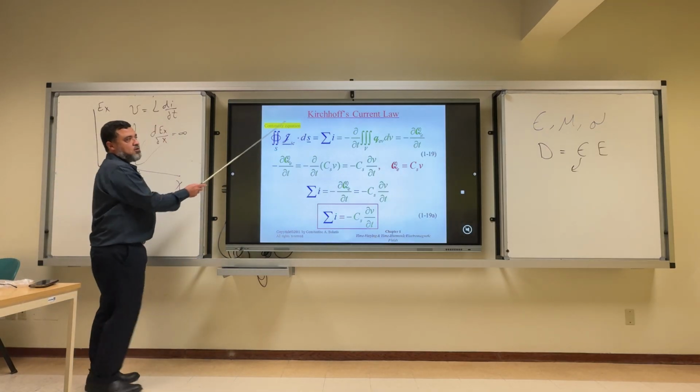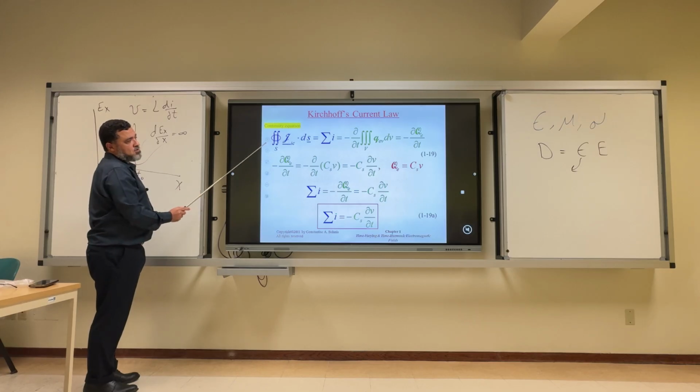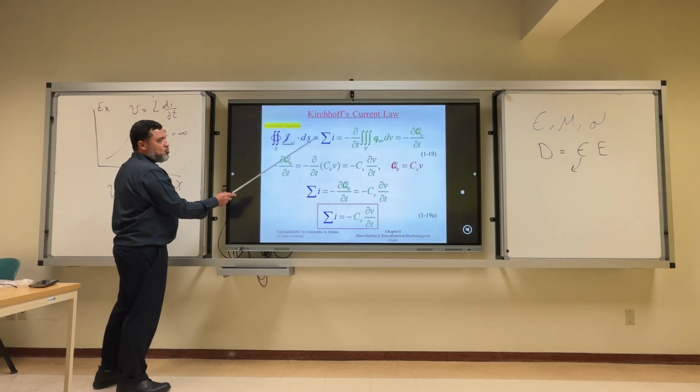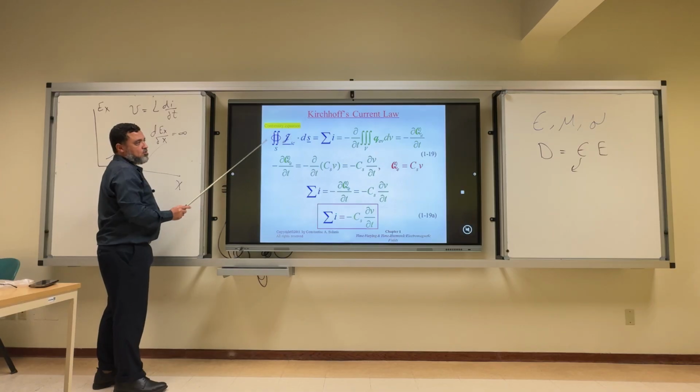We can do the same for Kirchhoff's current law, KCL. So we can start with the continuity equation, which is the closed surface integral of the electric current density. We have here J_i and J_c, the embraced and the conduction current density. The surface integral over a closed surface should equal the enclosed current, the total current at this point, which should be a very small volume, like a node in a circuit. This has a unit of ampere per square meter.